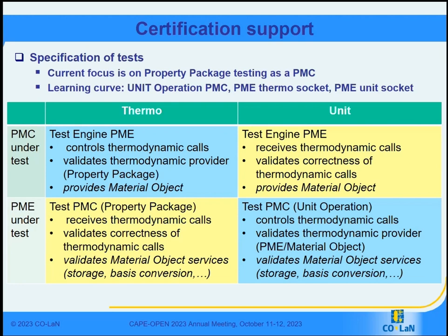Still, it has to be mentioned already here that there are some other components within the CAPE-OPEN environment that exercise thermodynamics calls: unit operation PMC, PME thermo socket, as well as PME unit socket. And in the table presented on the slide, you see the symmetry as well as asymmetry for different components or interactions between the components to be considered.